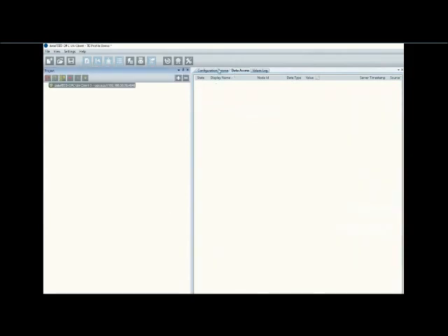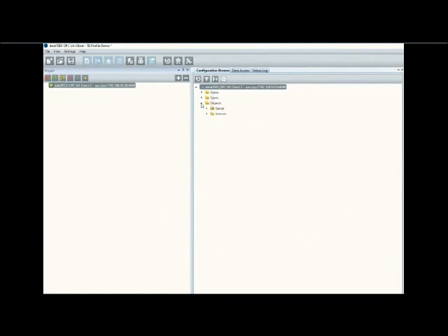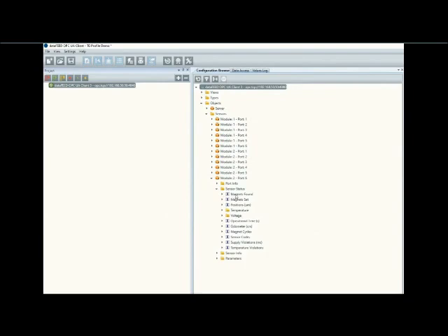And that's all I need to do at this point. And all I have to do from there is to decide what OPC UA specific Industry 4.0 data I want to access. So going down to this folder called Objects, I can look at the list of sensors that are available. By the way, that folder structure is identical no matter which OPC UA tool you use. It's always a views folder, a types folder, and an objects folder. And you're usually interacting with your data in the objects folder that is there.